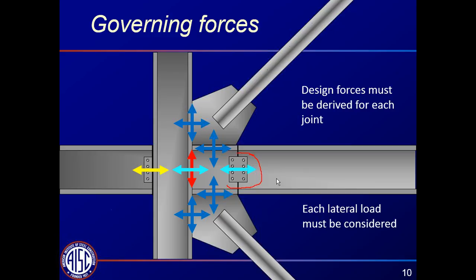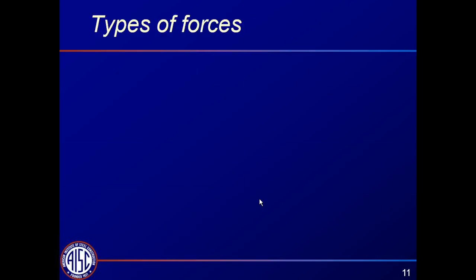But the method does give us the axial forces in the beams as well. This joint could be a pin sort of joint, as I've drawn here, or a fixed joint. If it's a fixed joint, there are also moments to be designed for. Those are not included in this methodology, but it's pretty straightforward to carry those through the connection and doesn't really require any comment.